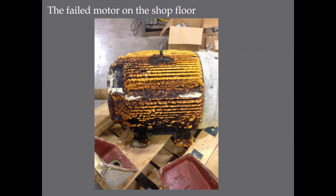PM. Here was a motor that failed on a shop floor in a company I was at. So I asked the maintenance, it's sitting on a pallet, failed motor. I said, why did the motor fail? Oh, it locked up. Bearings went out. Well, that's probably a generality of why it failed. But what do you think happened here with temperature? The same thing I looked at on another picture here.